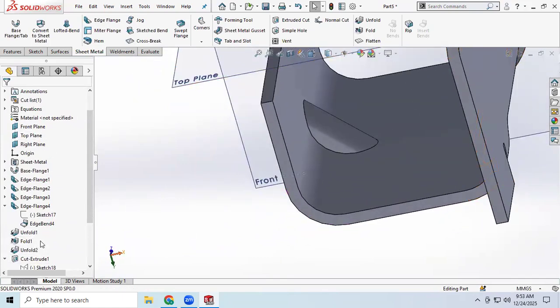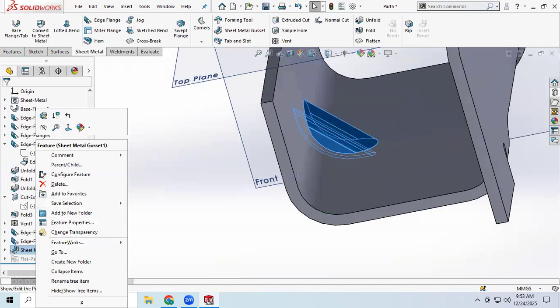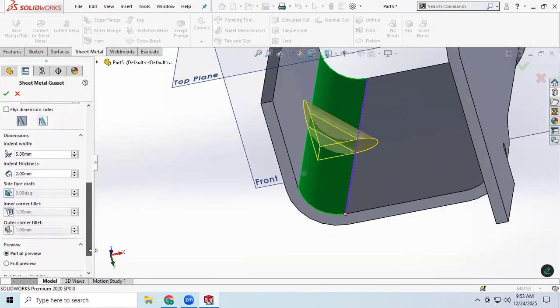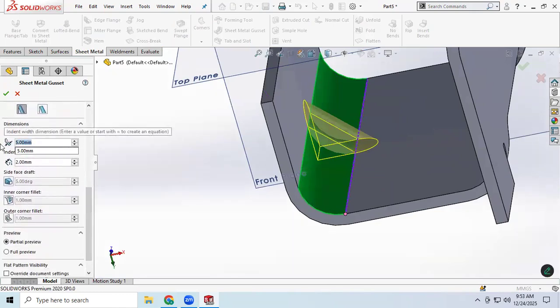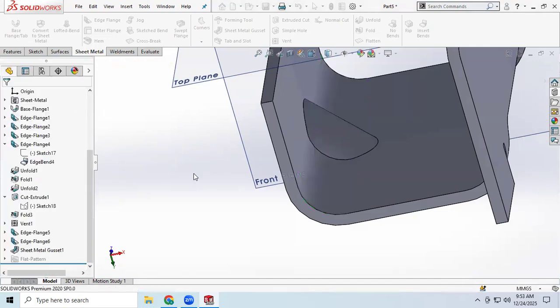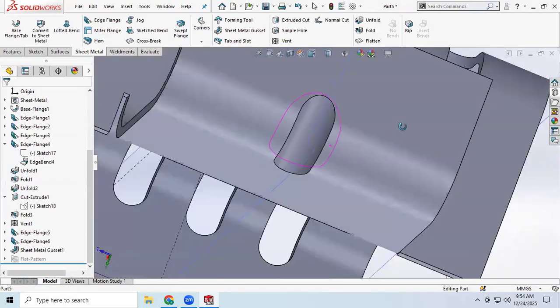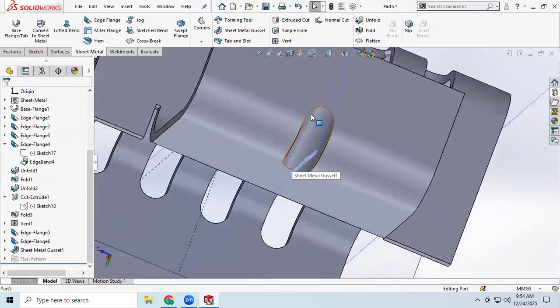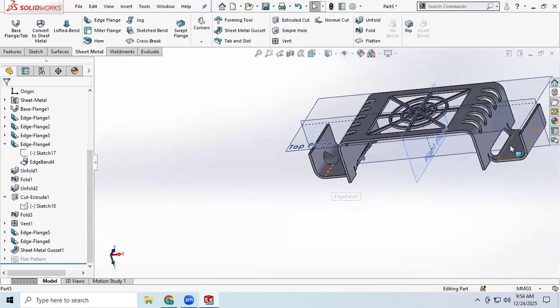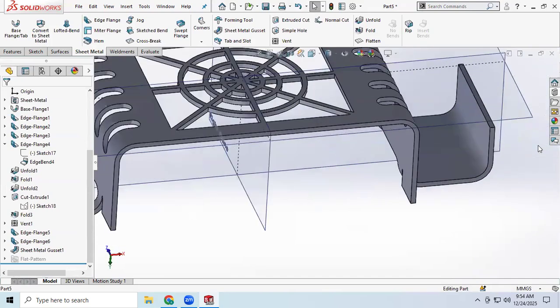I just want to do one thing once again to see better. I go to edit it. And this I want to do. That's 10 out. And your thickness is 5 mm. And if I click here, this type of gusset goes here, and then this type of face you can see here in your objects. By using this way, you can create this type of thing. The same thing you can create here. So you can also create this one in this portion also. This is simple.